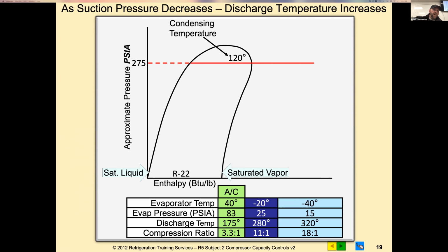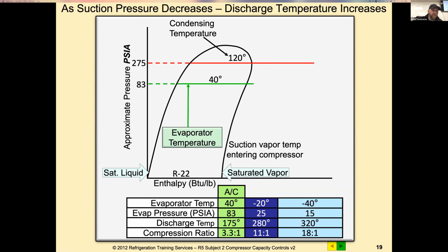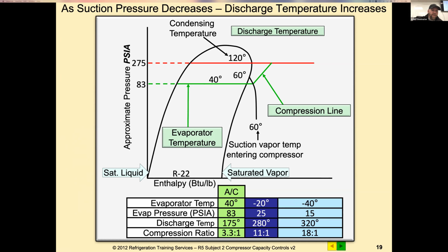So 275 PSI. That top red line that you see that just showed up, that's your condensing line. Your bottom line, that green line, that's your evaporation line. And that angled line is your compression line. On the straight down line, right there on your refrigeration effect, that's where it goes from a discharge to a liquid and then goes through your metering device somewhere in that black line on the way down from the condenser line to the evaporator temperature.